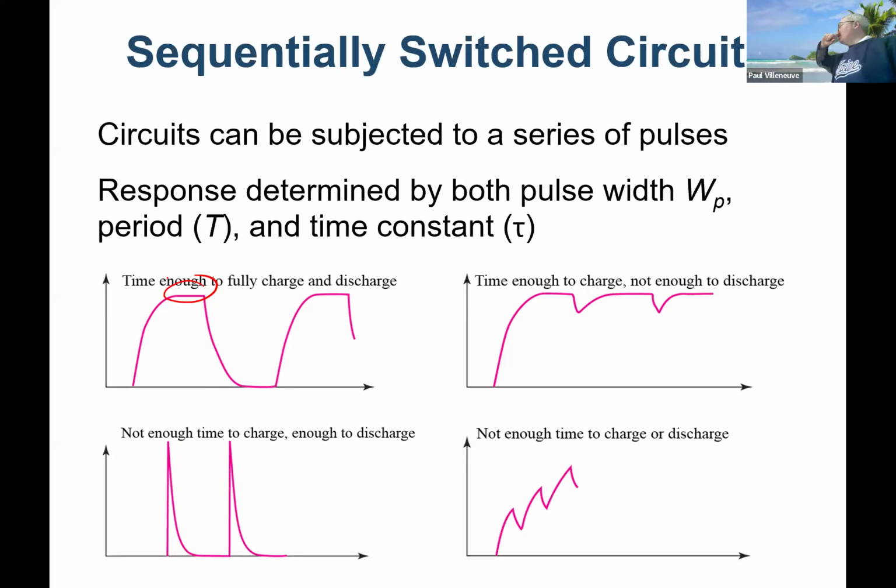If you want to keep this charged, like in the case of a bridge rectifier, everybody know a half wave or full wave rectifier bridge? You want to make sure that you don't completely discharge the capacitors across your bridge. You can see that over here. You've got the positive sine wave that has charged up the capacitor fully.